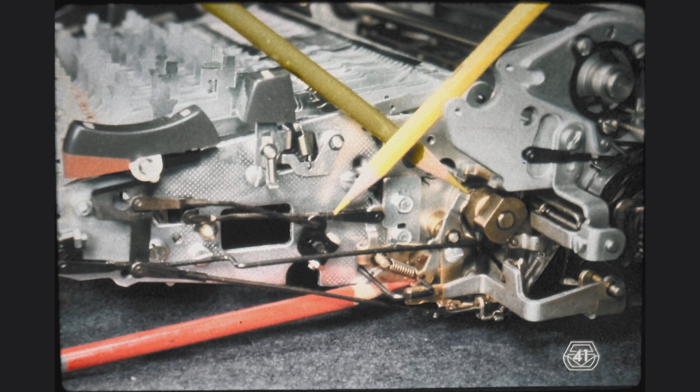The velocity control cam follower, green pencil, must be allowed to select a low printing velocity for characters with a small printing surface or area. During any printing cycle, the cam is made to turn with the filter shaft, but before the cam follower can follow the cam, the input section must select low velocity printing for that particular printing operation. Only symbols such as the period, the comma, the underscore, and a few others use this low velocity selection mechanism.